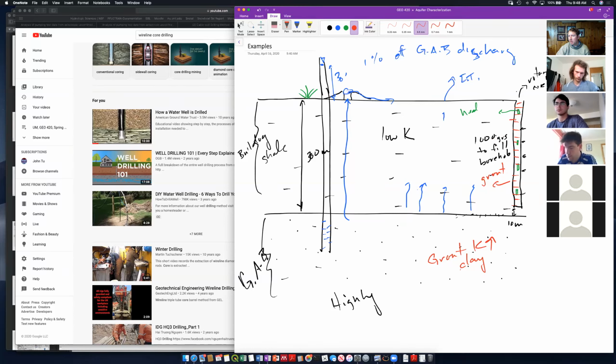So after about a month, my pressure transducers are recording the pressure in the fluid just outside the clay. And the reason why is because we grouted it in. All right. And we only had to transmit the pressure pulse through the porosity in our grout.